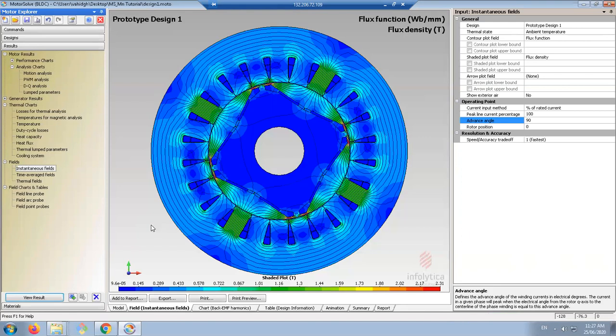The flux level decreases, and that is this concept called flux weakening, which is used wherever you want to increase the motor speed beyond its rated or nominal value, which is always the case in transportation applications like electric vehicles. For example, we already set 3000 RPM as a rated speed. But if you want to go beyond 3000 RPM, a method called flux weakening is applied in order to weaken the flux so that the motor will be able to operate beyond 3000 RPM.